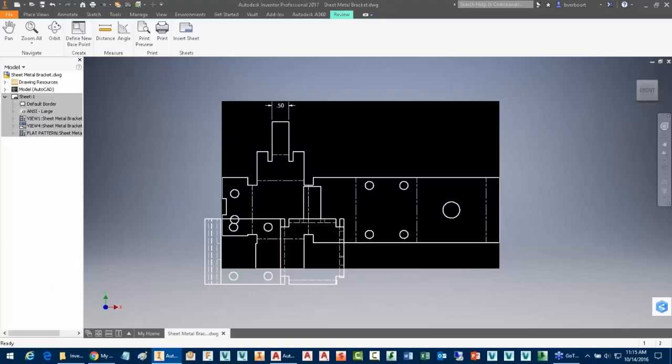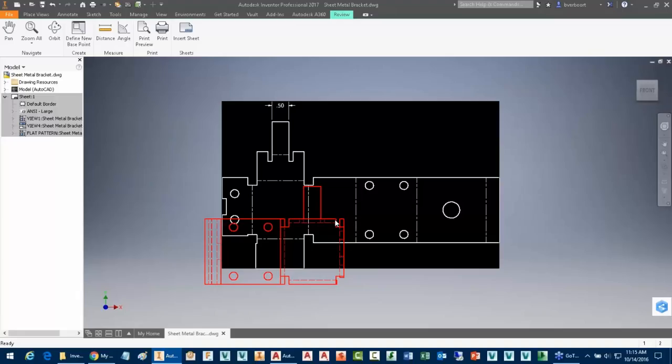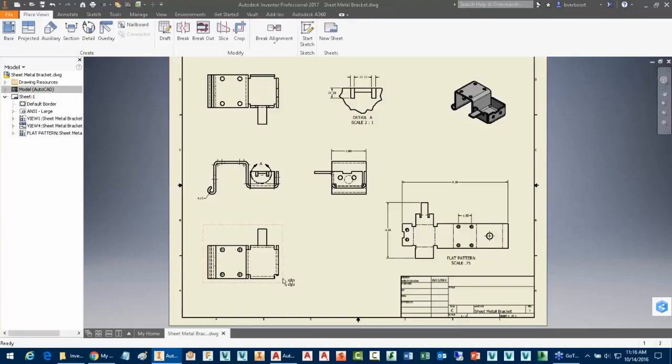Right, so I've now actually added in a couple views, one on top of the other. And again, those are blocks, so those could be arranged next to each other if need be. But there's a much faster way to accomplish this task without having to go in and select each of the views independently and then rearrange them, if you will, if you're looking for an AutoCAD file. The point here is to not take the Inventor drawing and export it as a DWG file, because that then breaks the link between them. So it's nice to keep the integrity between the DWG information that's being consumed and the Inventor environment that's really the source or the creation tool for that.